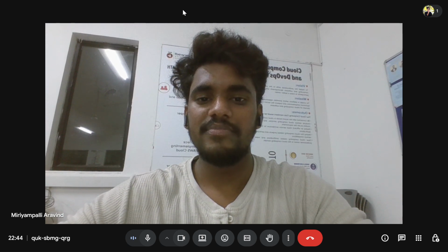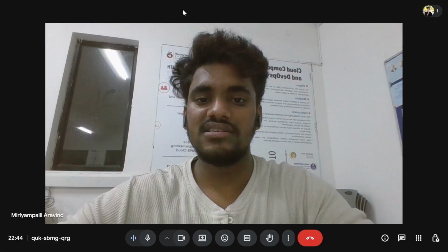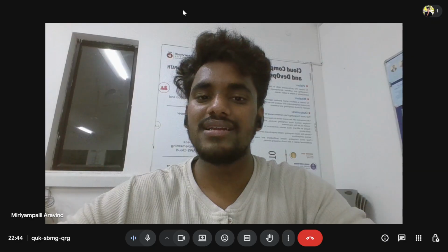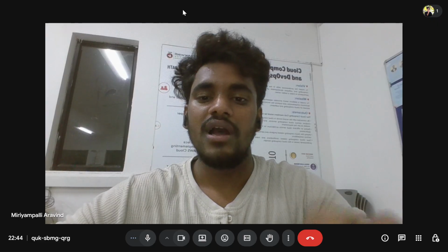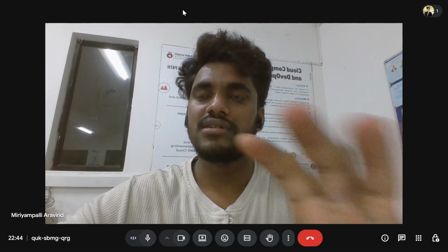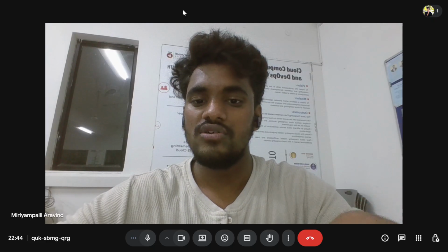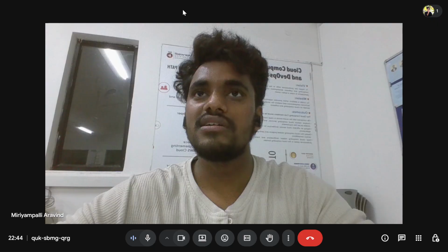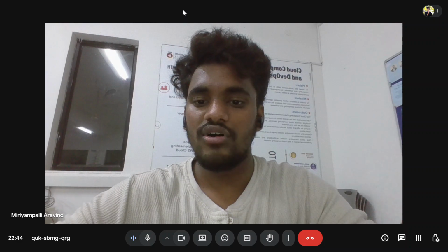Everyone, my name is Arvind Niyampalli and I'm going to present my AI-based project titled VoltAI, where we do IR drop prediction using deep learning. The main aim of my project is to predict IR drop in VLSI chip design using artificial intelligence. IR drop is the voltage reduction that occurs inside a chip due to resistance and high current flow in the power delivery network. If the IR drop becomes high, it can affect chip performance and reliability, and also the clock signal with the operations.